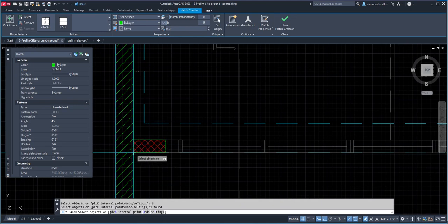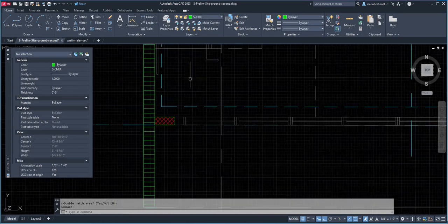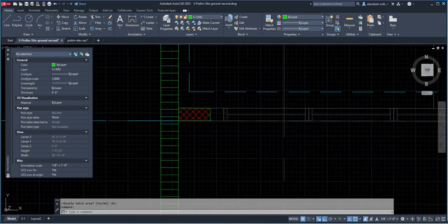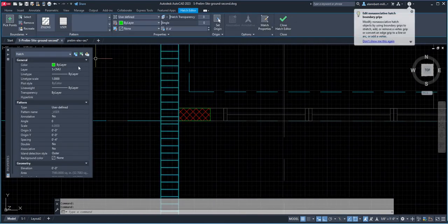Now, sometimes the engineer will decide that he doesn't want these kinds of CMU angles. Let's just change that. It all totally depends. So we're going to just put a 0 here and press enter, and there you go. Now let's say adjust also to 4 inches. Okay, and then close. And then select that and change the color to not ByLayer but red.